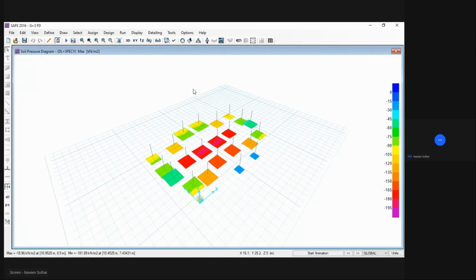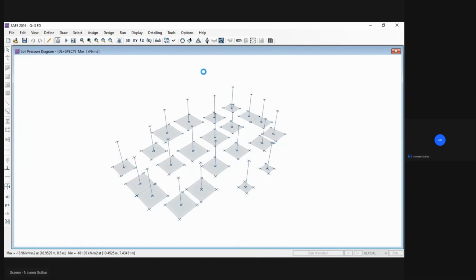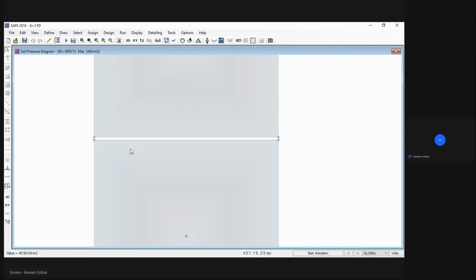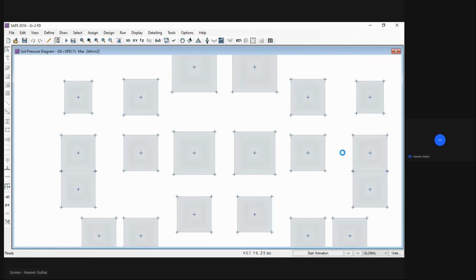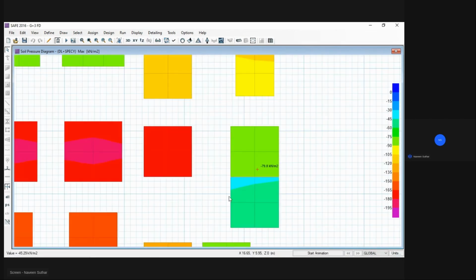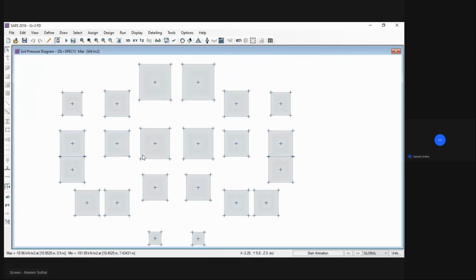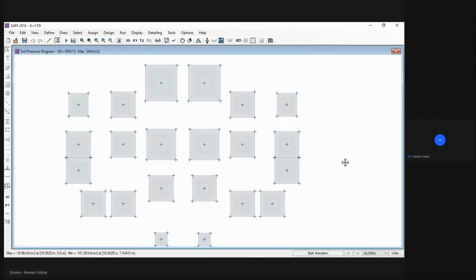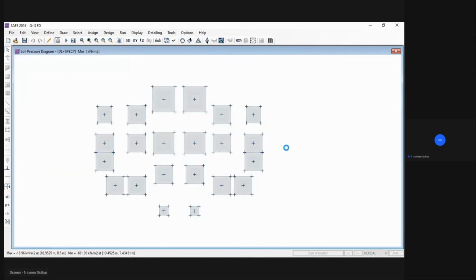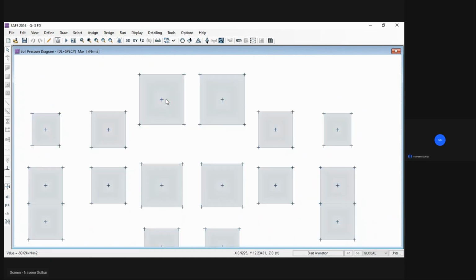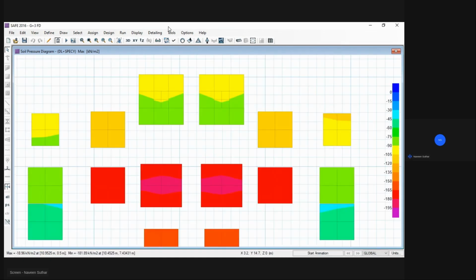And now I think it's a final foundation for our structures. Here you can see you can merge the area. You can merge this, so that will be a combined foundation, and you have to design the combined foundation for that. So that's how. So you can see it's 90%. It's for dead load plus live load.